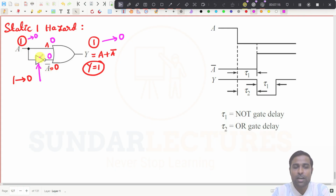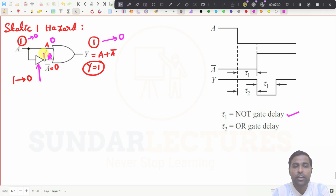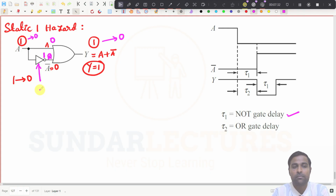And what happens now? That is what I have just written here. This tau 1 is the delay created by this particular NOT gate, right? Now what happens after the delay? This 0 is going to become 1, and now this is 0 and then 1. What happens here now?